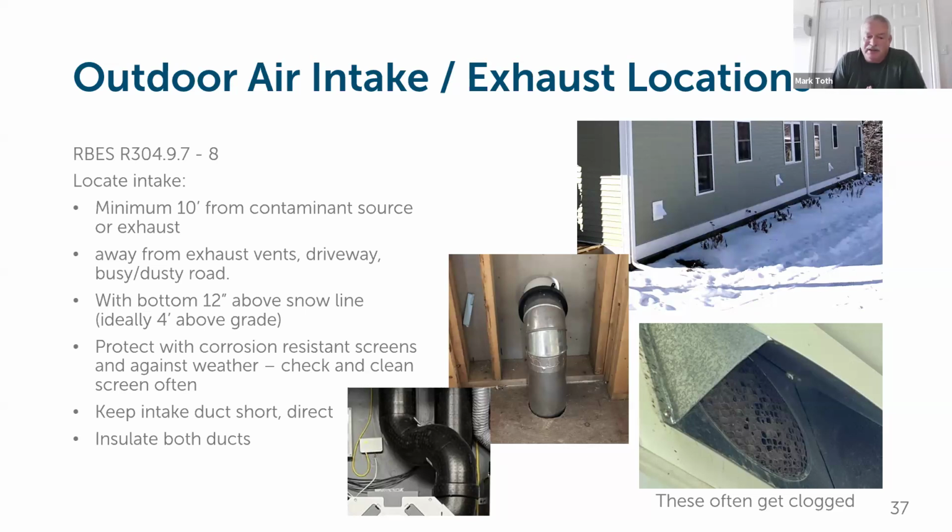Your vents need to be cleaned regularly. The goal is to keep these a minimum of 10 feet from a contamination source for your intake air. Your intake air is extremely important. You're bringing that air in the house. So when you think about contamination sources outdoors, we have to think about boiler or furnace vents. We have to think about dryer exhaust, range hood cooking exhaust, bathroom fan exhaust. We don't want our clean air coming in from anywhere that's not clean. You've got to be at least 10 feet from any contamination source.